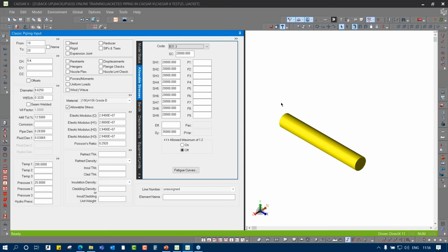So this is what it will be changing. The first thing, the node numbers. Let me activate my node numbers. This is the default node number, starting with 10 to 20. If you want, you can follow the same node numbers, or you want to change some node numbering details, you are free to do that. The node number sequence is something which the user is going to set, and based on that everything is going to come out. Based on the convenience of our modeling, the node number variations and increments can be set as per our requirements. Some prefer to have the increment at 20s, some prefer the increment at hundreds or 50s. So it's up to the user to decide the nodal increments and the start node numbers also.